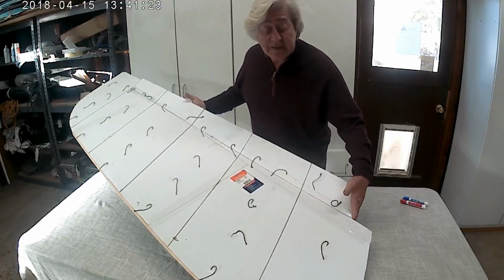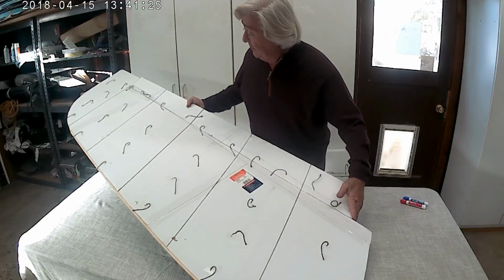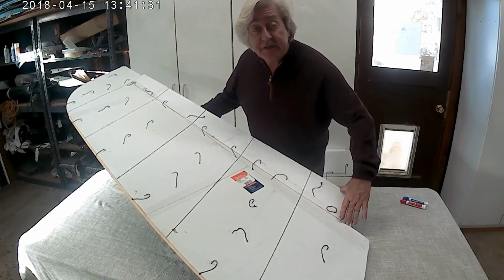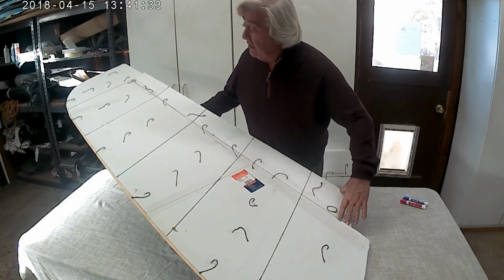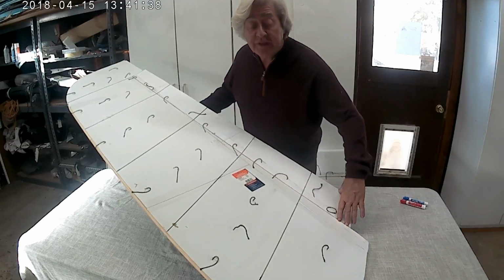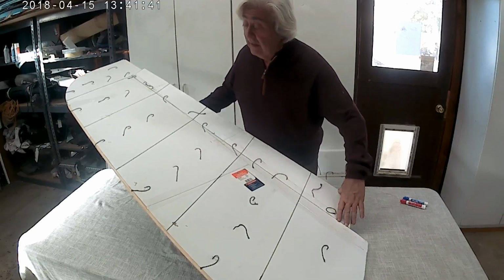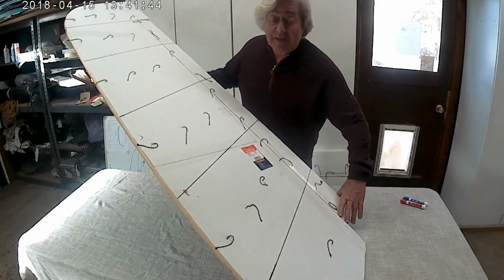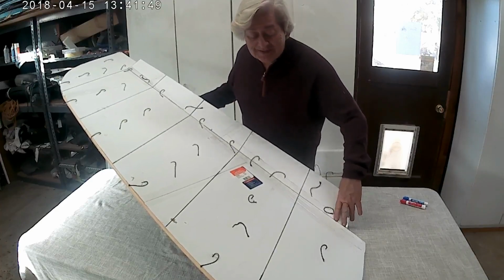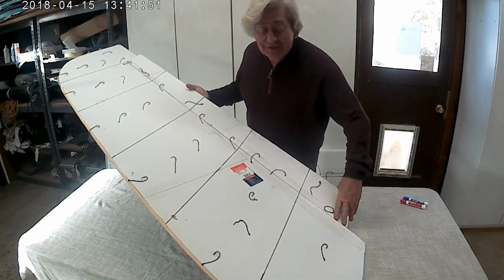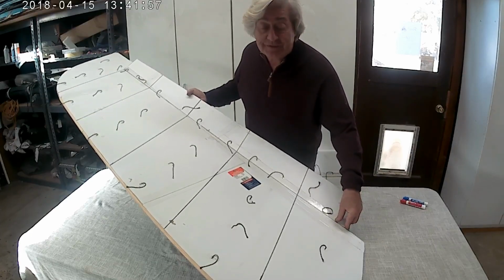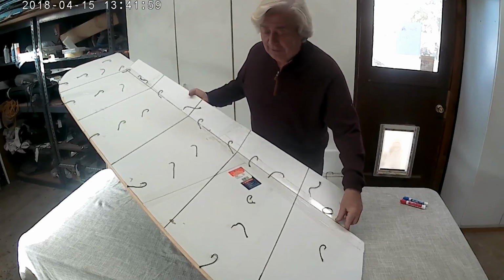Okay, here we are with sample number 1 of the elevon shape. This is pretty much a standard control surface shape. It's a certain percentage of the chord of the wing. This is a full-size mock-up of my wingtip panel outboard of the winglet. Yeah, it's a flat plate airfoil, but for what we're doing here, that's good enough. I was going to build wing sections just for this test. It's good at low angles of attack, and we can study the flow conditions relative to the control surfaces, even with a flat plate. So let's not worry about the lack of airfoil.